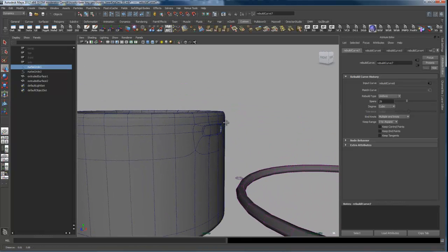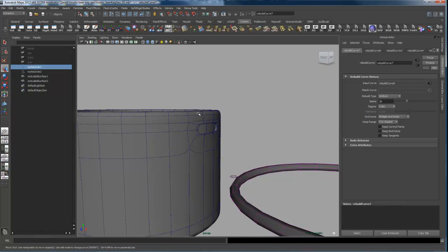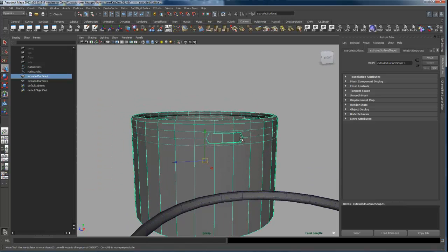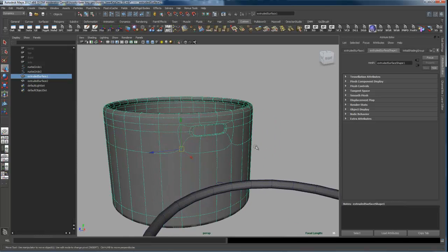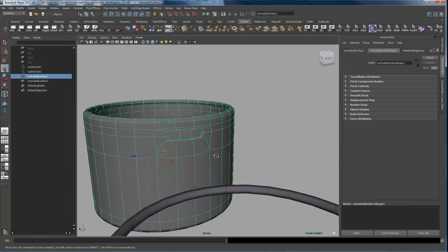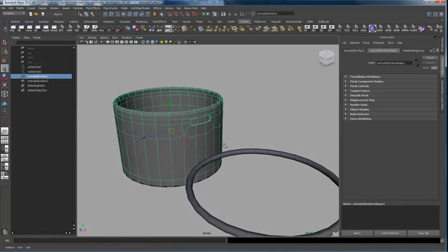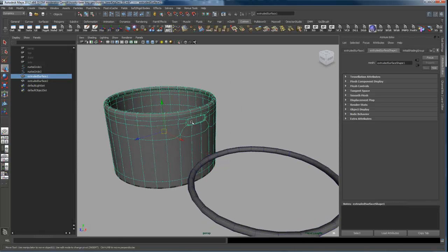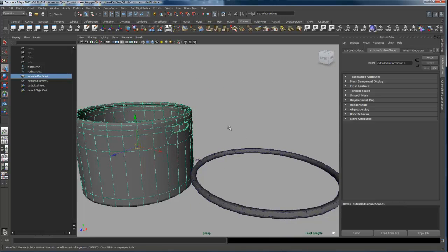The reason is that I'm going to use this as the upper part of this can, and pull it down. I want to create this hole for the handle, but I wanted it such that I had 2 edges running through this handle, so I get this proper rounded shape at the end of the handle. And also I wanted to maintain the shape of the can. So I picked those 30 sides because of this handle and the requirement to push the handle in and wanting to have 2 edges that run through the handle.